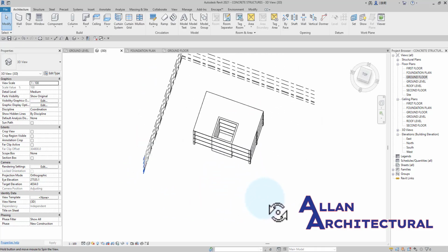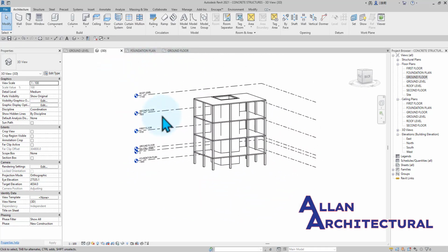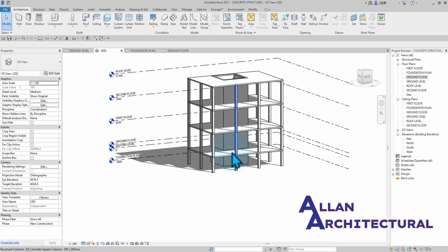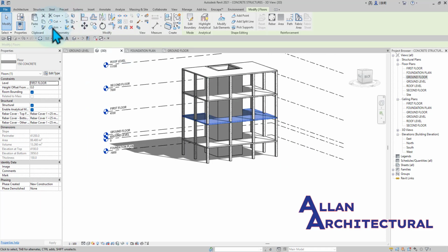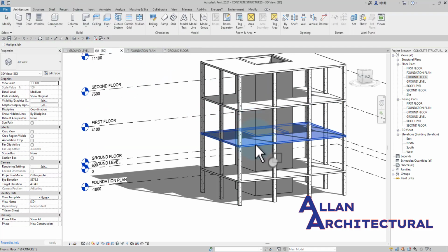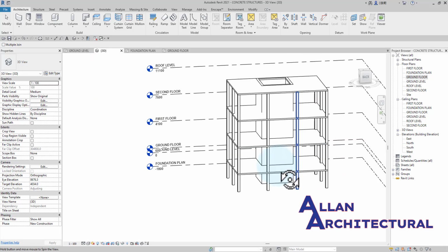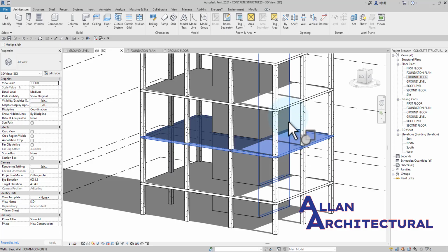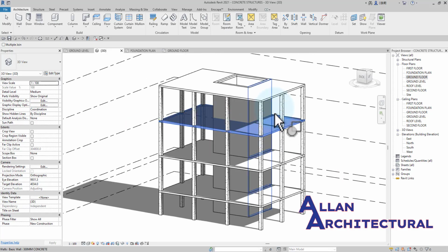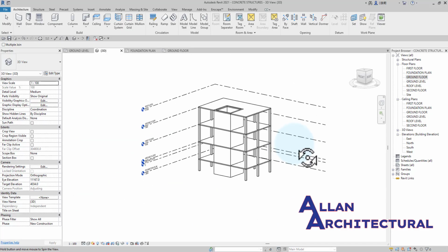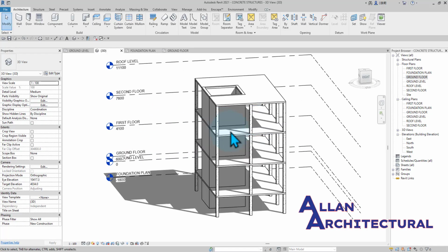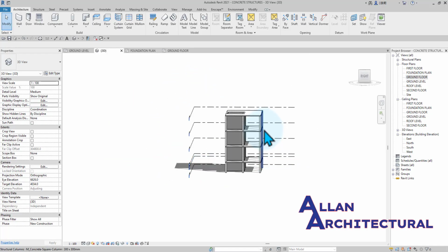All right, so we have that hole in there, so that floor slab doesn't look like it's covering through every space. All right, so same thing, you can do what we did for in there. You can just click on your join tool, just click on that slab, join it with this, click on this slab, join it with this wall, and let me just do this on the other side, click and join it with this. So you can click in here, join it in there, click in here and join it in here, and you can click in here and also join it in here as well. With the back, I don't think we have a problem, and this is perfect. So we have this in here.